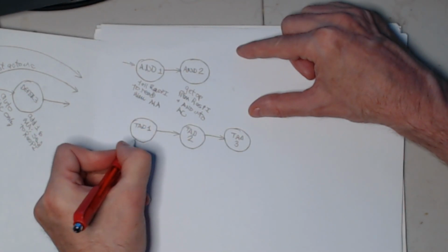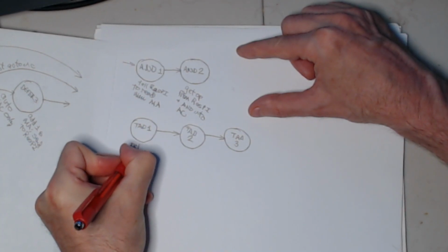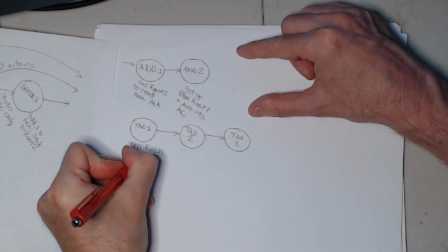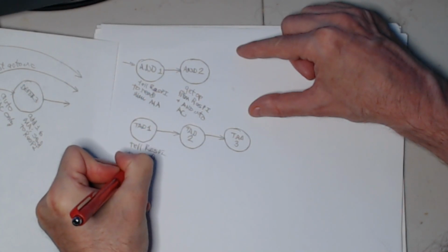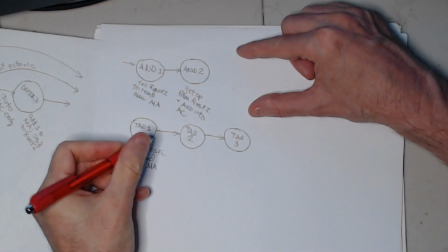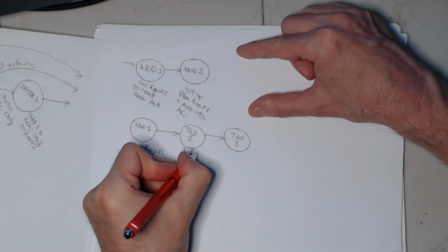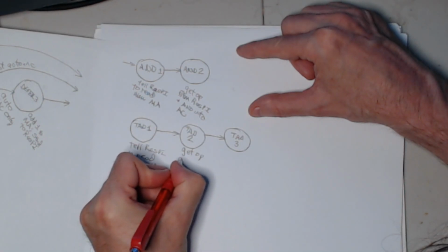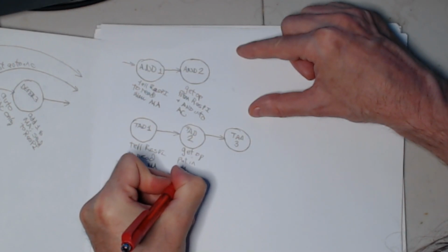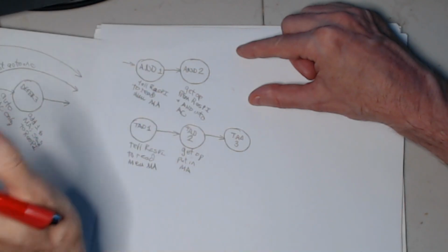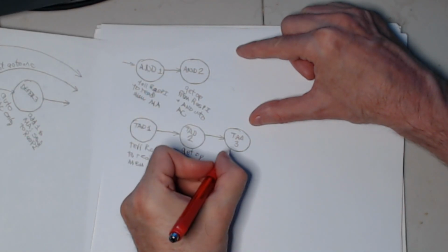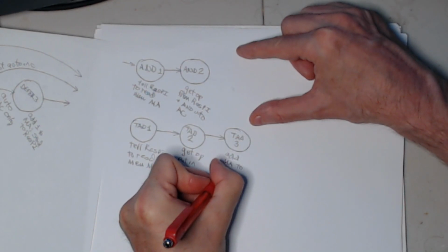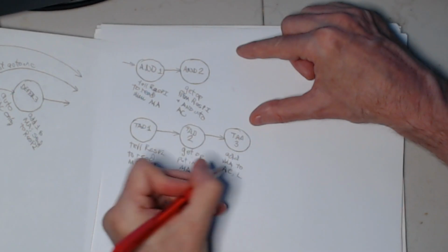Okay, so again, this is telling the Raspberry Pi to read memory with the memory address register. And then this gets the operand, and it just sticks it in the memory address register. It's not really a memory address, it's a memory value, but well, just call it the MA. And then here we add MA to the accumulator and link, so we can say and link, right?